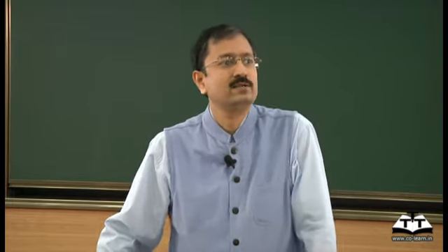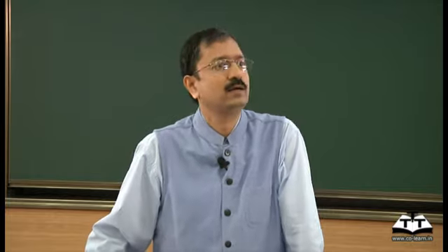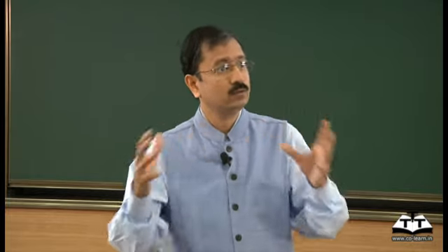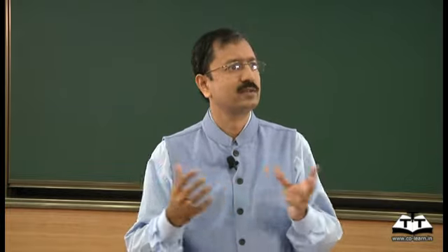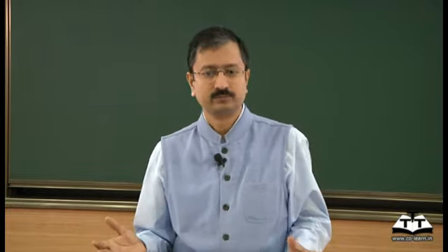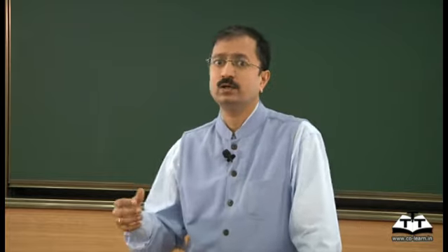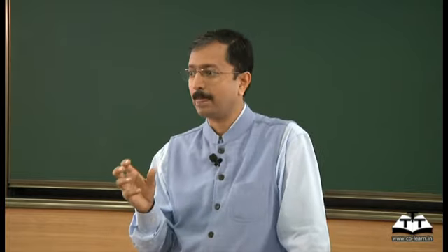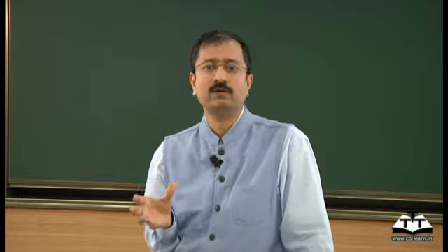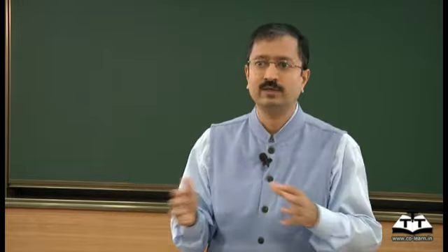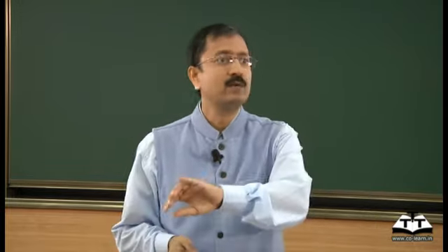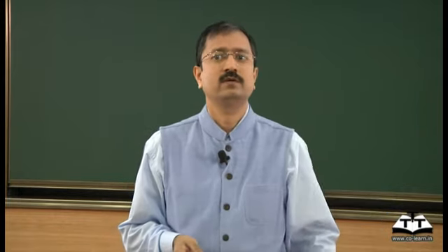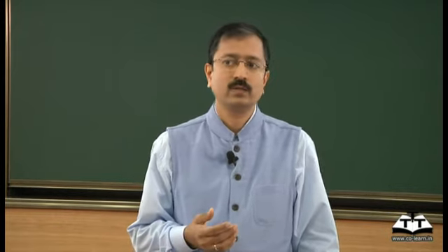And I must tell you that these days we have very nice equipment available for full 3D geometry, like white light scanners, laser scanners, 3D scanners. CMM is also there, but the scanners are very fast. With a white light scanner, you just scan from all different directions, and your software builds the entire geometry, and you can compare that with your reference geometry of the as-cast part.